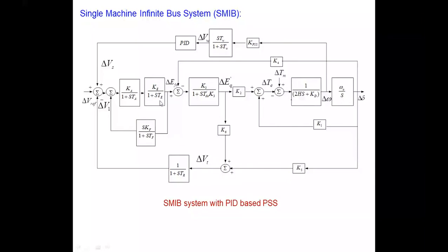So this difference will be the input here. Then that means you can apply a step change here. Let's say you want to observe the state variable. How does the rotor angle change? So this is your output variable, right? So you can apply a step change, some 1% or 2% or 3% change in the turbine mechanical power. Then you have another input here.